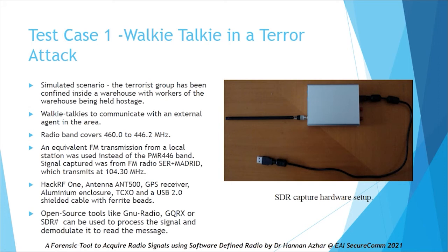In this case, it's receiving in this example. And then we have this cable here, which, you can see, is a shielded USB cable, and it has the 3 ferrite beads here, 1, 2, and 3. These are to suppress the high frequency electromagnetic interference, so that there is less noise and less interference.